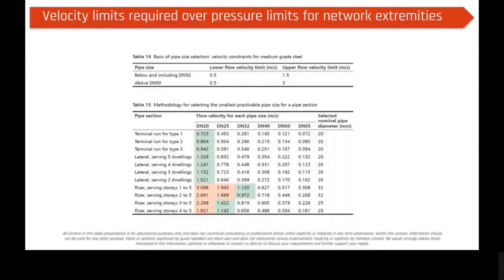As you come back from the dwelling and corridors and also down the riser, obviously your length of pipework is starting to get longer and longer. That's impacting on your index run and the selection of your pump in terms of the head and differential pressure it needs to put into the system. And so eventually you will move back to more of a pressure drop based approach.